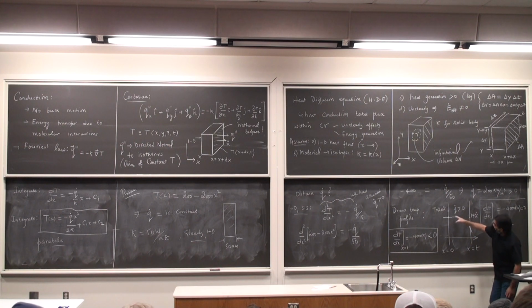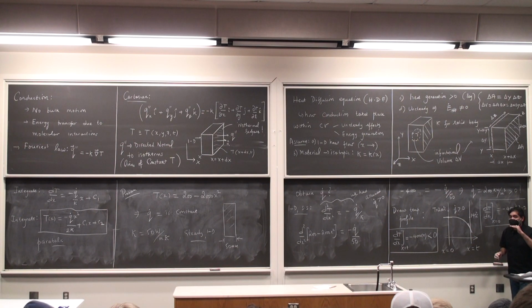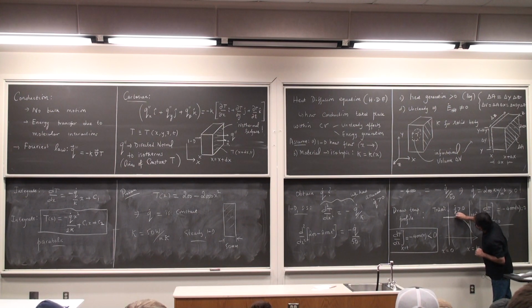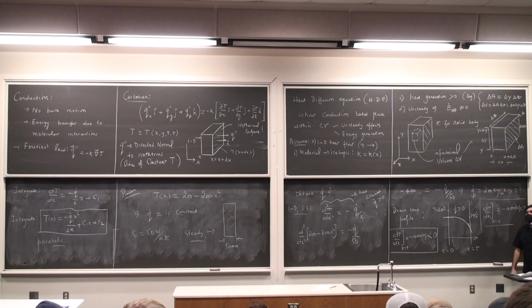But as I start going from the left to the right, my temperature profile says that I am descending, and this completely makes sense because the direction of heat transfer is in the direction of the negative temperature gradient. So at each and every point, if I draw the slope, I am slowly going downhill at a constant rate, or at a linear rate. I'm sorry, the slope is not constant, the slope is linear here. First derivative is linear here. So all of these things are really important to understand. We're going to spend a lot of time just looking only at profiles, no numbers, no equations.